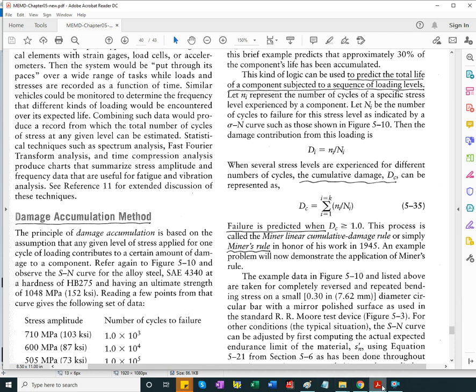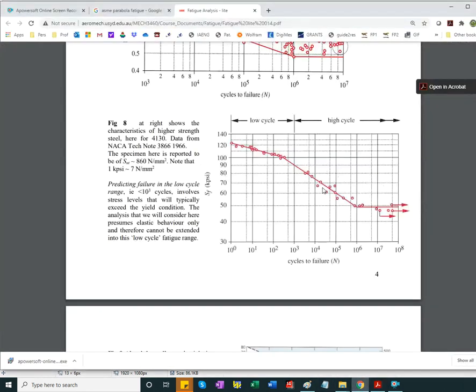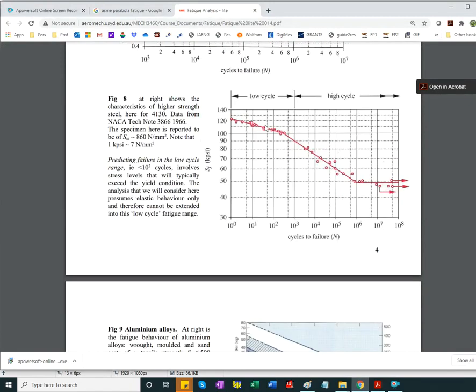This assumes that we are under the sloped portion of the graph, so you don't design for infinite fatigue life. Sometimes that's not economical. I'm sure you agree, if you go to a junkyard and take apart a vehicle that has been on the road for 250,000 miles, you can find components that are like new and could be used over and over on other vehicles. That's not an economical design, to have parts that can last way more than is needed.